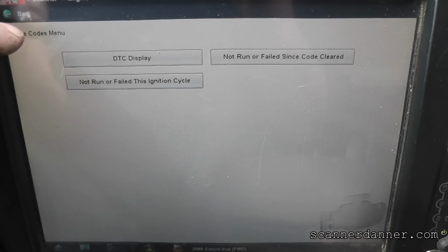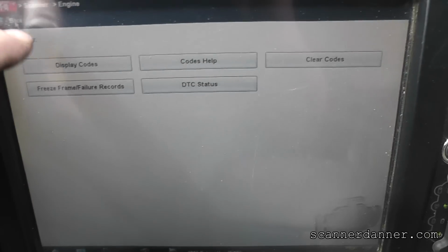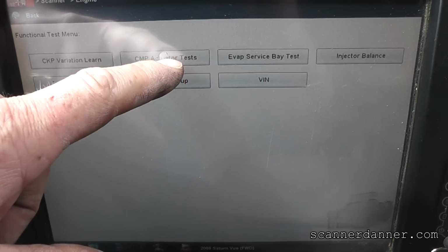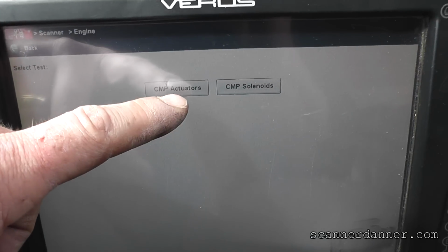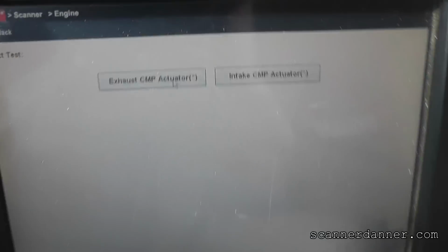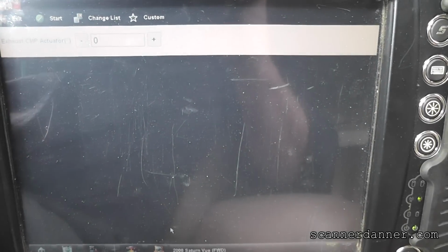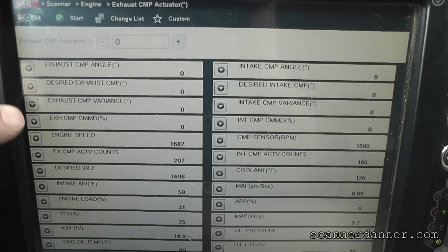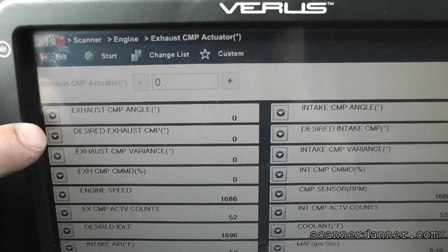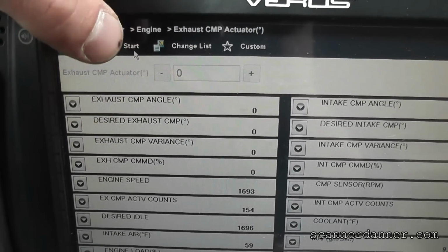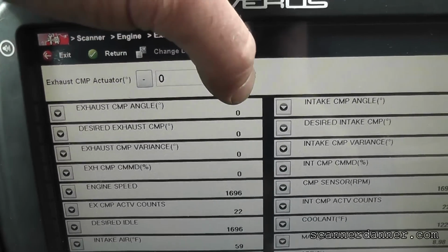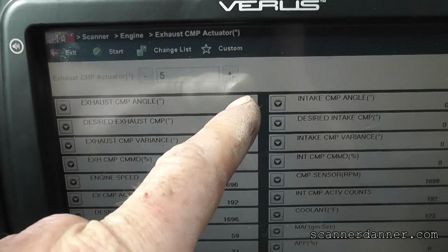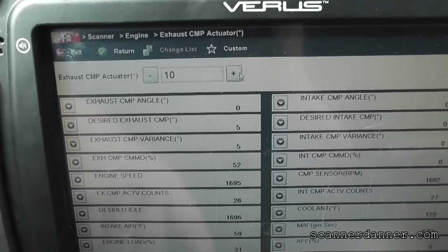And I'm going to go back and we're going to redo this actuator test that I started with, and it's going to be the one where we change the percentage and already raised the RPM. And we'll just focus on these first 3, as I hit start and then I change the percentage. We want to see a corresponding change on the camshaft.